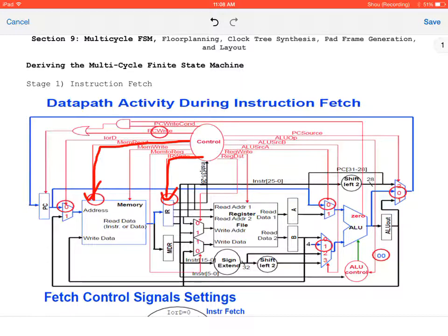Additionally, we're going to start initializing ALU source A here because we're going to increment the program counter. I should note the difference from this particular diagram, where it says 4. That's because in the 32-bit instruction, we'd have to go PC plus 4 to account for 4 bytes. In the data path I presented to you last class, this is just 1 because it's just 1 byte, so I will only want to increment by 1. That's the difference, but we are going to add this.